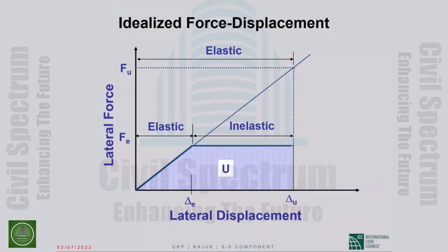We don't need a high degree of inelastic deformation capacity. Seismic design is always a two-part affair. Design for the forces that we have chosen to design for the strength level, and detailing for the inelastic deformation capacity that we must have in order to be able to design for the force level that we have chosen.